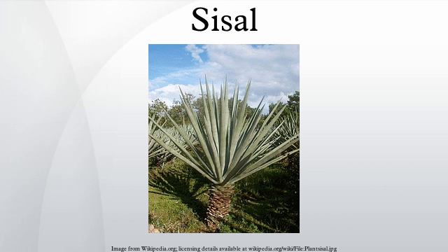Fiber extraction: fiber is extracted by a process known as decortication, where leaves are crushed and beaten by a rotating wheel set with blunt knives, so that only fibers remain. In East Africa, where production is typically on large estates, the leaves are transported to a central decortication plant, where water is used to wash away the waste parts of the leaf. The fiber is then dried, brushed and baled for export.